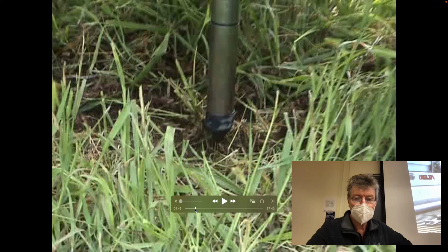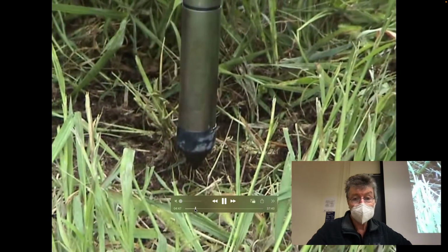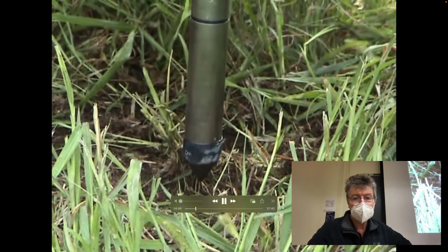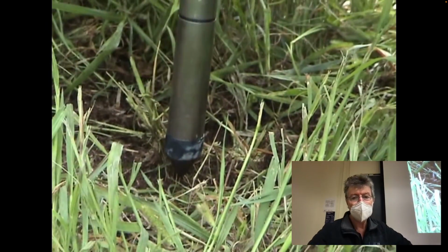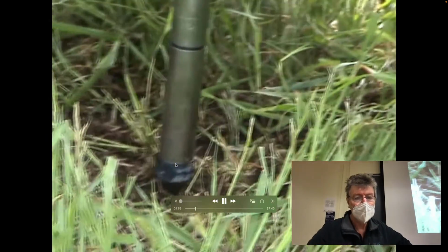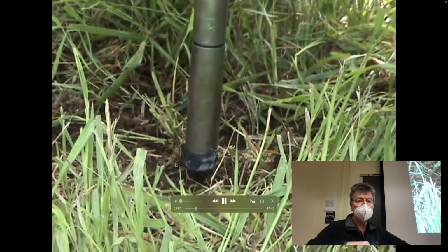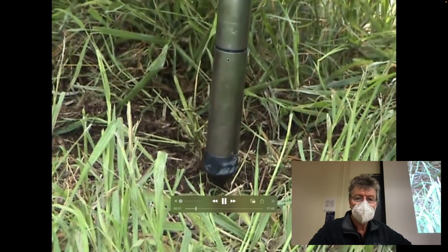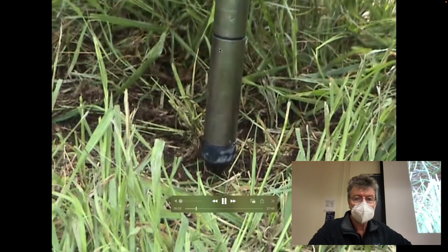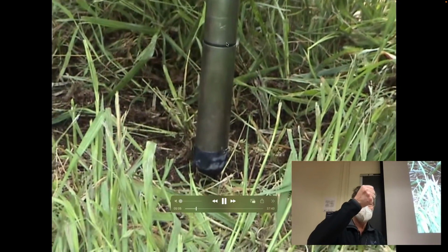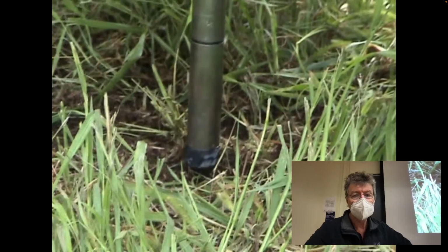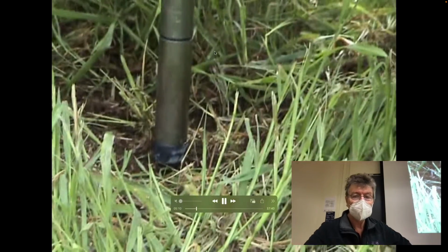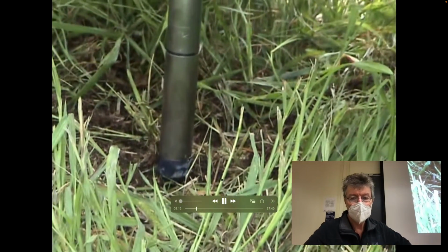And the wrinkle on this particular implement, you see it exactly here. This is a piece of bicycle inner tube wrapped around the element to keep it saturated. As soon as it goes into the ground, it'll just get ripped off by the ground passing around it. This is the load cell at the top to measure the two loads of the tip and the sleeve friction, which we can use as a proxy for the material we're going through.